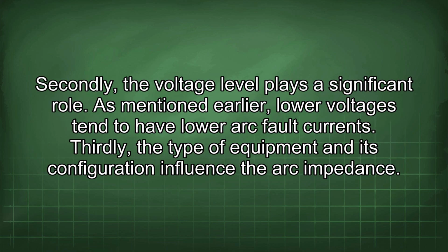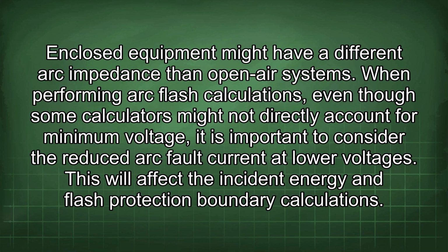Secondly, the voltage level plays a significant role. As mentioned earlier, low voltages tend to have lower arc fault currents. Thirdly, the type of equipment and its configuration influence the arc impedance. Enclosed equipment might have a different arc impedance than open-air systems.